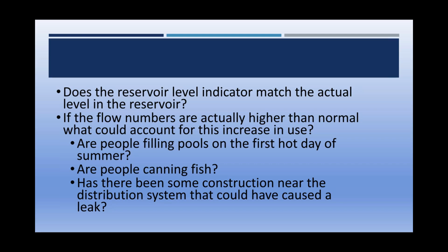I had a system where we would test the hydrants for flow. We would test, for instance, static pressure, when it's just a pressure gauge on your hydrant, which, as I mentioned earlier, you can use when you're trying to find leaks between isolation valves. And then we would turn on the hydrant and check the pressure and get what's called a dynamic pressure. And there's a ratio between these two things. We found that although the static pressure was good, the dynamic pressure was low, and we had no idea what the cause was.